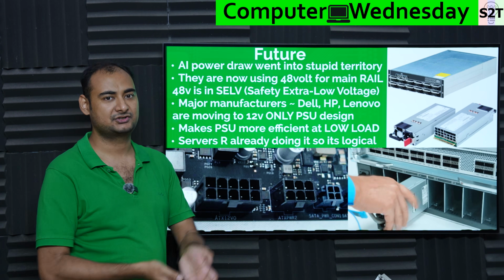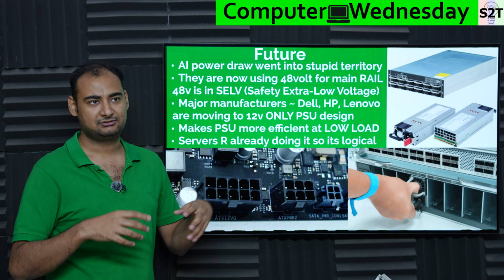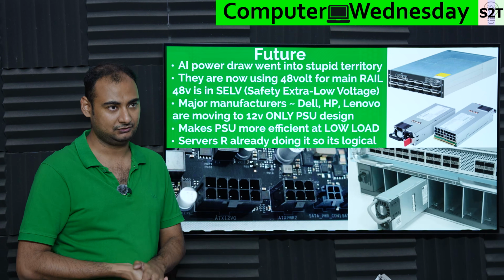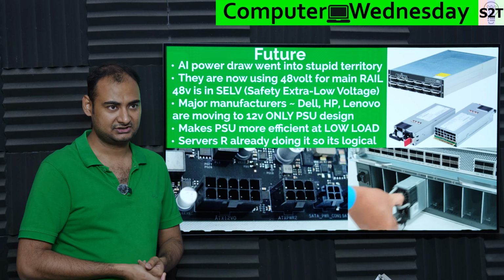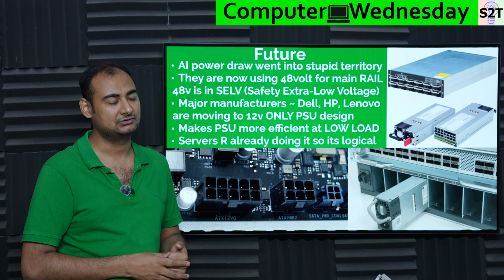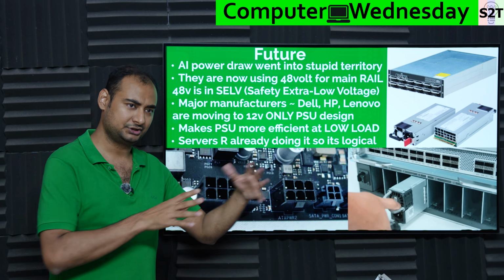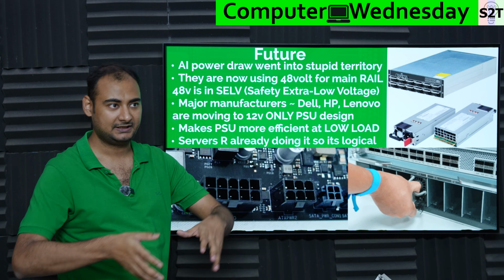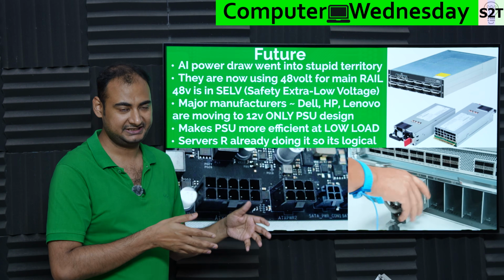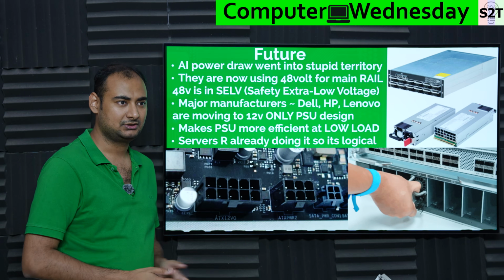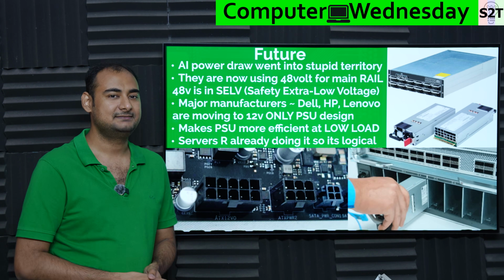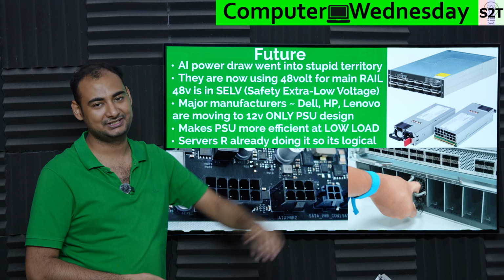You must have seen people trying this. Mercedes has this, where it's like, okay, 12 volt system, throw it away, put in 48 volt. Tesla also does that, a 48 volt system on the Cybertruck, and newer trucks will also do that. More people are doing 48 volt. Look into USB power delivery, so to say, PD. The 3.1 standard has 48 volt. But why exactly 48 volt? Yeah, that's below what we call safety extra low voltage.